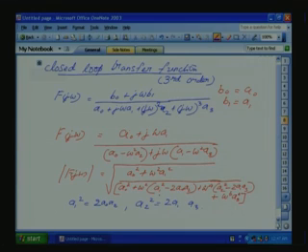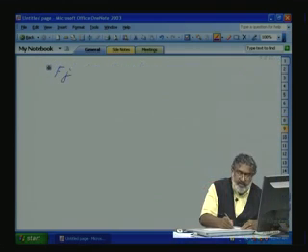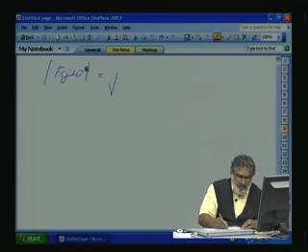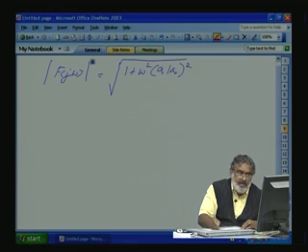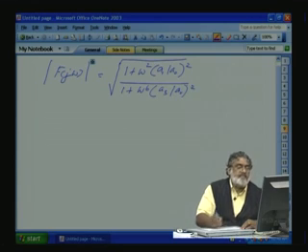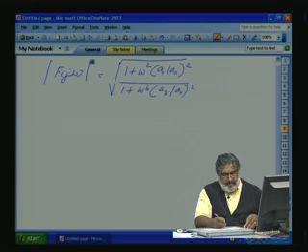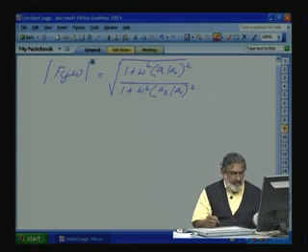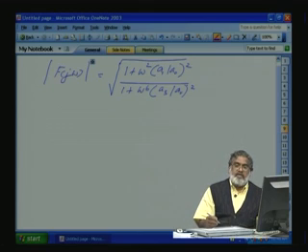With this, what is the final output transfer function? So based on this condition, the final modulus will be, well, let's go to a new page, the modulus of F(j omega) is equal to root of (1 plus (omega A1 by A0) square) divided by (1 plus (omega cube A3 by A0) square). This way we will get it. So this is the way we can do it for the third order system.